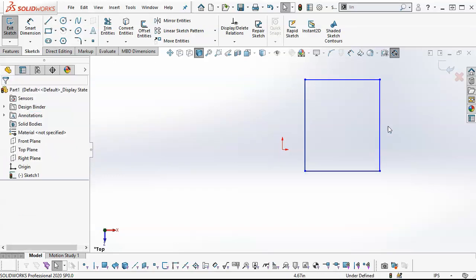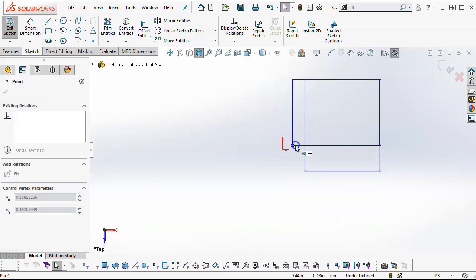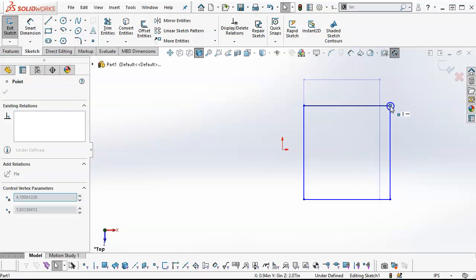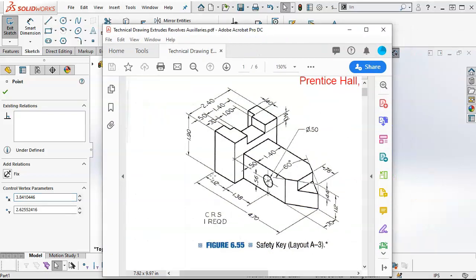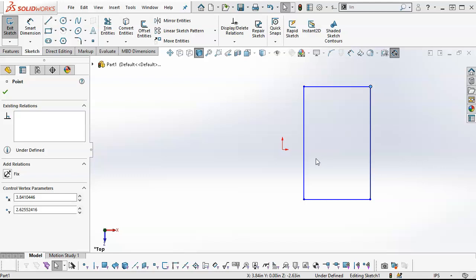And when I look at this, everything in the geometry is in blue. And so as I drag that around, it's not staying defined. It doesn't have any dimensions. There's no real form to it. So when I'm looking at this figure, what I'm trying to achieve is going to be this rectangle across the bottom base and then the extrusion up. I could have just as easily drawn the rectangle this way and gone both directions and then built the geometry out of the front. So in this one, since I picked the top view,